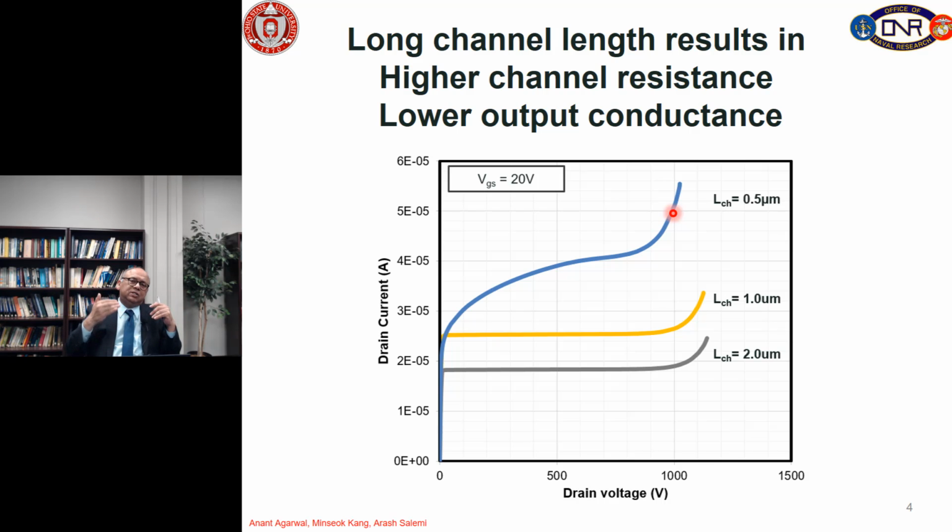The temperature will rise so high that the aluminum overlayer will melt, the passivation will peel off, and basically the device becomes a big black chunk of carbon. So the application standards are that this device should last for 10 microseconds without getting destroyed if it were to be short circuited.